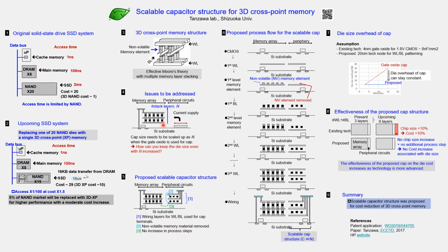the original concept for the 3D cross-point memory is to keep the area for the array, but increase the density per area. Thus, even if you can do that for the array side, you cannot do that for the periphery area due to significantly increased capacitor size.